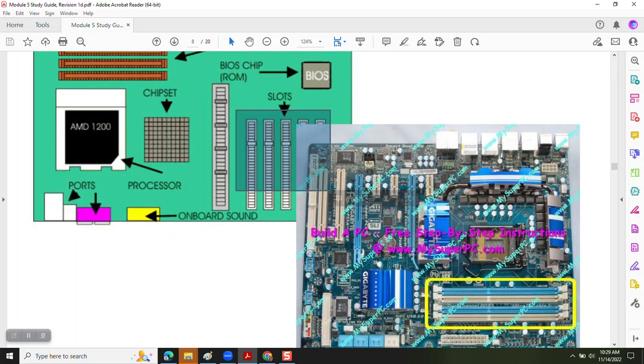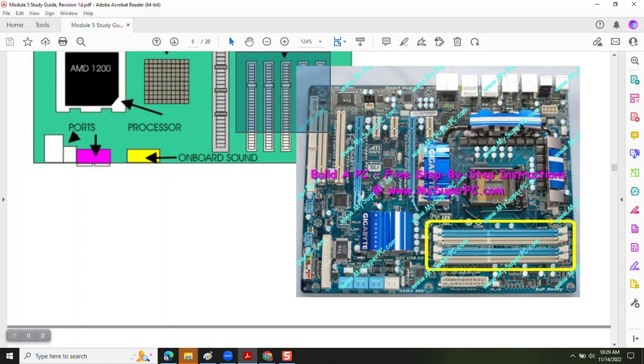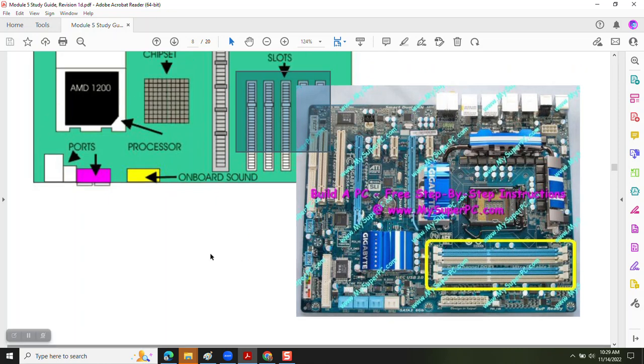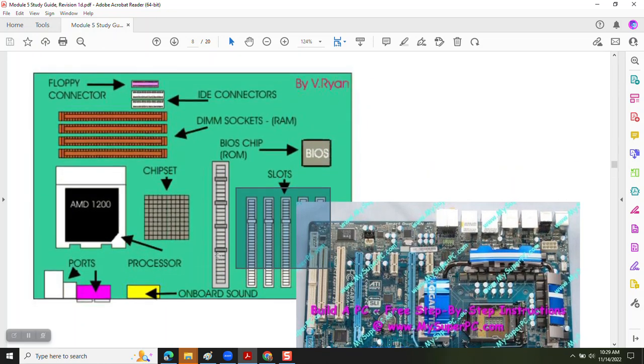So in this view, you have the CPU socket here without a package inserted, right? And then you have the RAM DIMM slots. This is where the memory modules for RAM go. And then over here would be a lot of the rest of the input and output for that system. So you get better at this the more you view different motherboard designs, but they all have the same basic pattern, and they track with the von Neumann model.